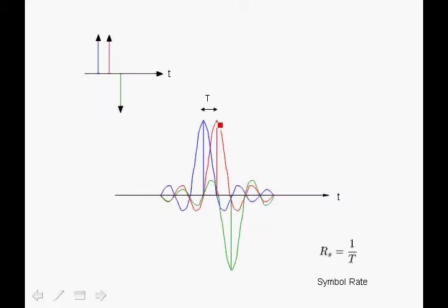So if we sample the signal at its peak, we will have 0 intersymbol interference, for example as shown over here. Now obviously if there's jitter in the sampling process, jitter in the clock, or errors in the timing recovery, then we will get a large amount of intersymbol interference, and it is only 0 when we sample at the optimum time at the peak, as shown over here.